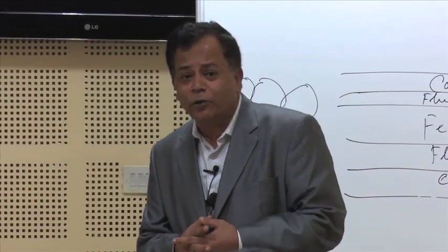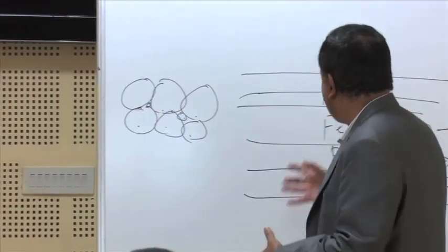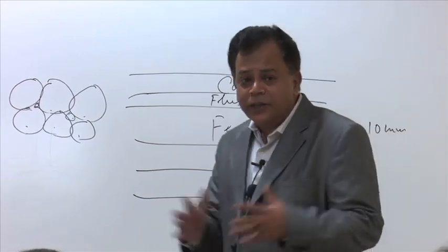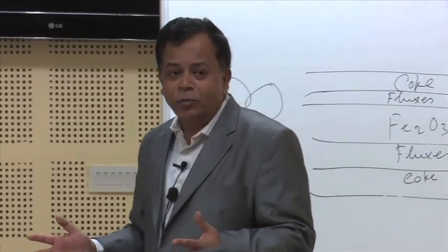So, that cake formation is there, and if it has got certain strength, there is some test, it is called caking index. Okay. So, there is some test, then if it passes through that and it gives you the confidence that okay, if I pour that material from that height, the nature of degradation will not be much, and it will help maintaining the permeability of the bed, then only I can accept it.